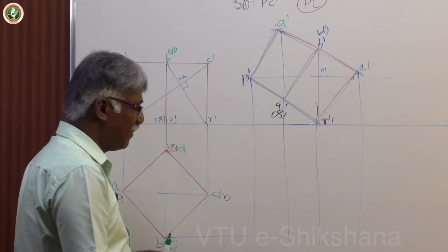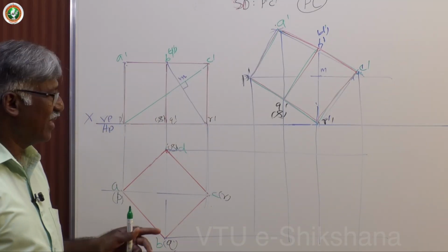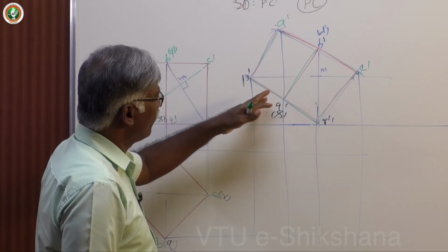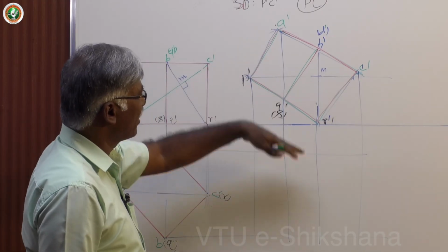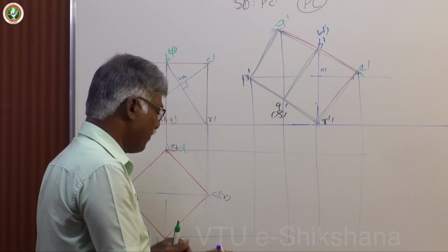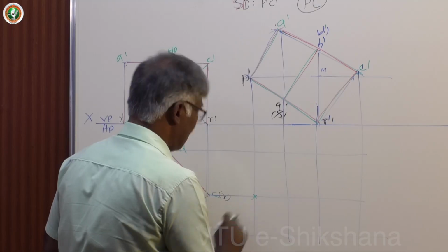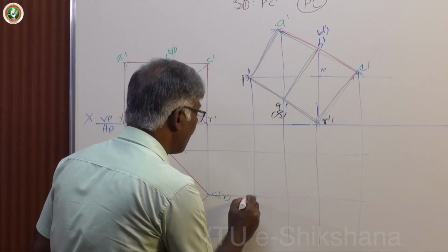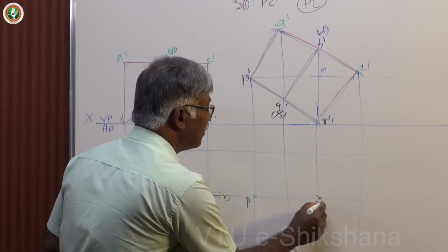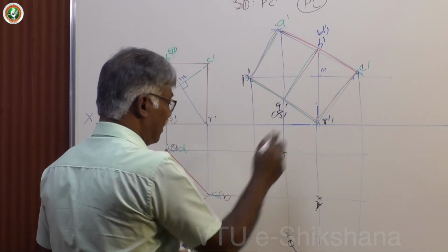Now see that the projections are very clear and you must do it neatly. And in case of computers, no problem because you are redrawing the same thing, but you should see that this is perpendicular. You get only 4 lines, 4 projections. Then draw. Now this is P, this one is Q, this is R, this is S. Base center. Join that.